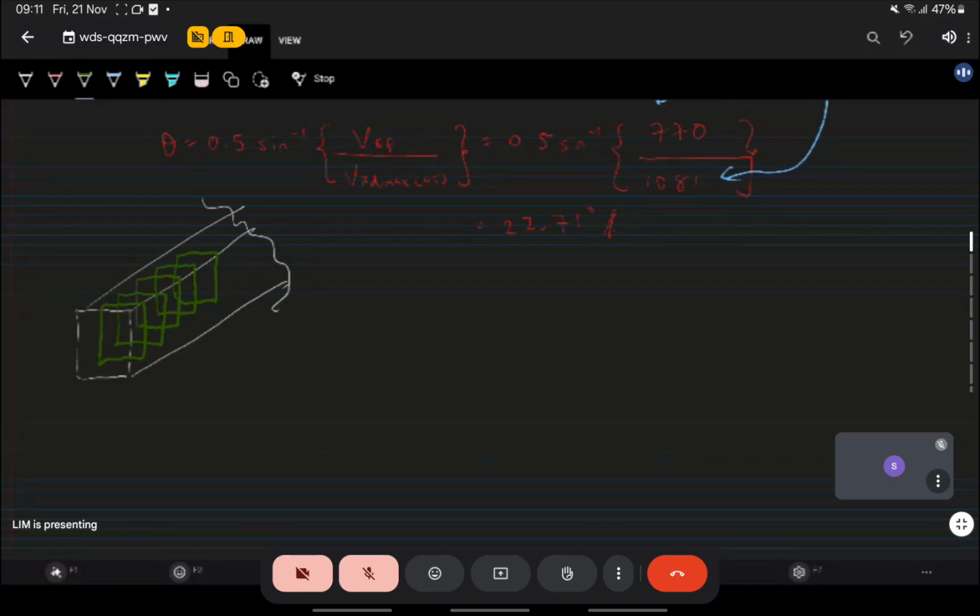So what they're saying is these steel bars, it's H12, meaning 12 mm diameter bars, and at 175 centers or spacing.